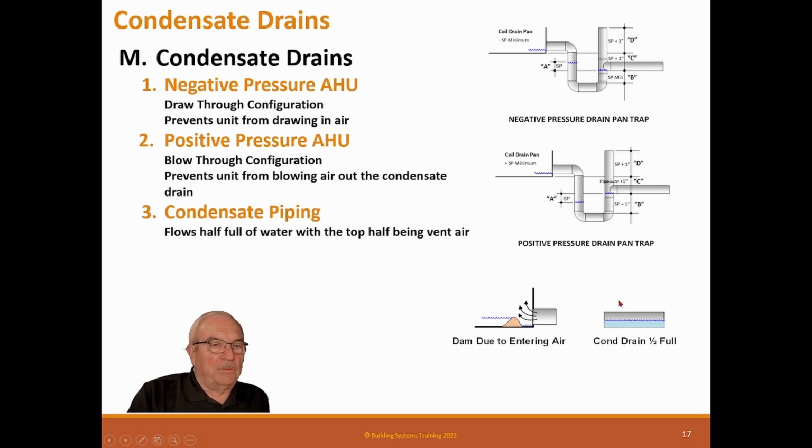And what a lot of people don't think about is that this seems logical until you put an elbow and turn it down, go down a wall or something. Now all bets are off because that pipe may fill with water because it's falling down. So you have to have enough area so that when the water flows around the pipe, it doesn't close it off. So condensate traps are really important.